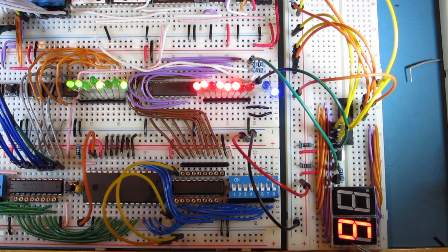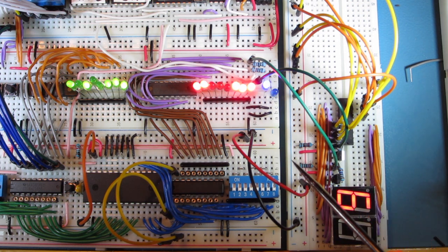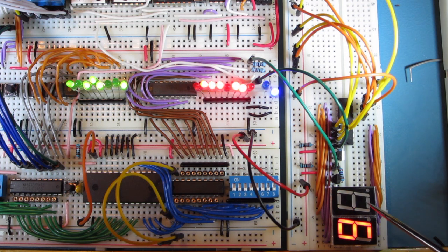All the segments that are the same are paired and fed to the same part on this pack of resistors, and then the other side of the resistor pack is then fed to either VCC or ground. If I want the LED illuminated, it goes to ground, and if I want the LED off, it goes to VCC. Now the idea here, as you can probably guess, is to multiplex the display, and the way I'm going to do that ultimately is through a